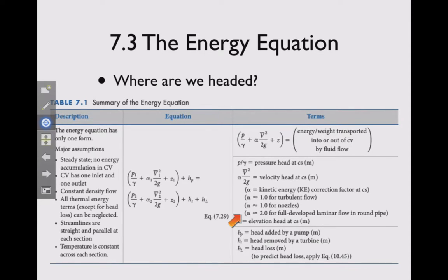And we will derive an equation for alpha that will let us calculate it if necessary, if we ever need to do that. But basically, it's related to the velocity and how the velocity is related to a uniform distribution of velocity. So we'll look at that in a minute. So alpha is new, and we're also using the average velocity, v bar, instead of v, because we're encapsulating the velocity inside this alpha parameter. We'll see that in a minute.